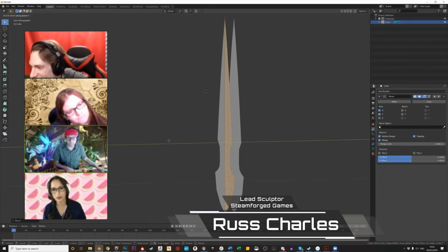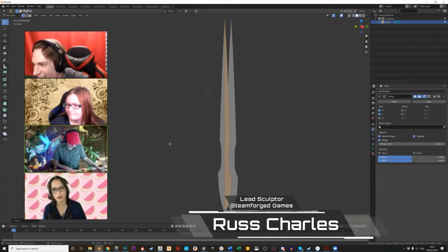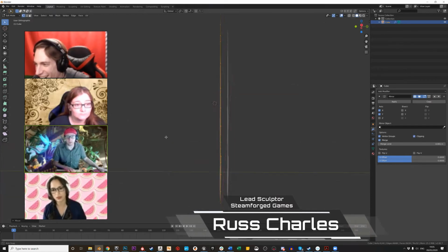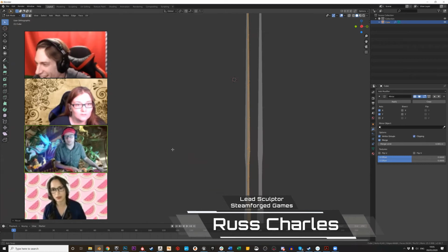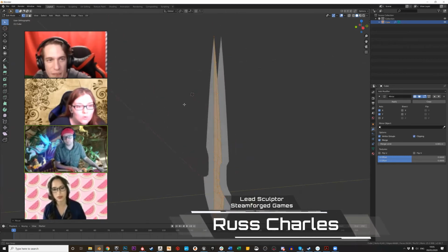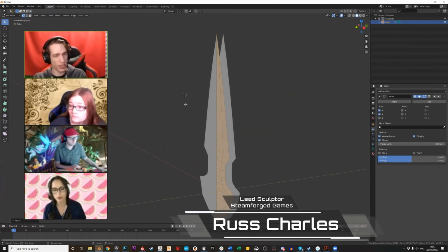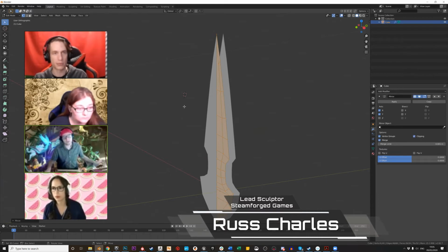Basically, we're just sliding these 2 objects until they are close-ish together. I'm doing this entirely by eye, which is extremely poor teaching on my part, but experience tells me that having them this far apart will give me a blade that's printably thick. And you were saying you want to shoot for about 2 millimeters? Yeah, you're looking to make the blade between 1.5 and 2 millimeters thick.